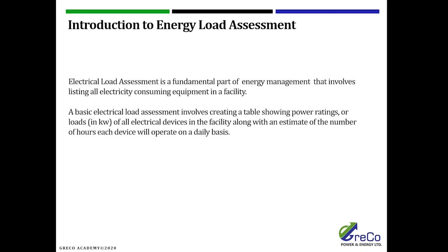The introduction to energy load assessment is one of the fundamentals of energy management. It involves listing of electrical consuming equipment in the facility. This is usually filled into a table showing power ratings and the load, starting from the wattage to the hours of use, taking cognizance of all the electrical devices in the facility along with their estimated hours that it will operate on a daily basis.